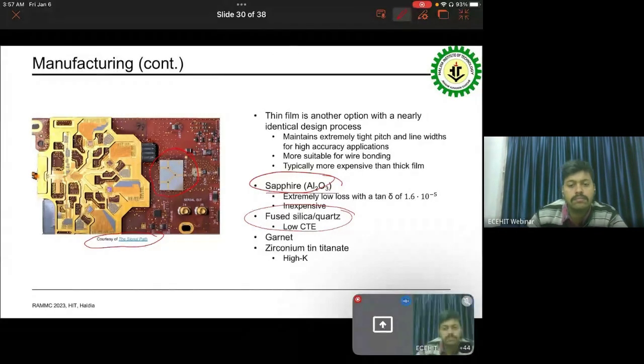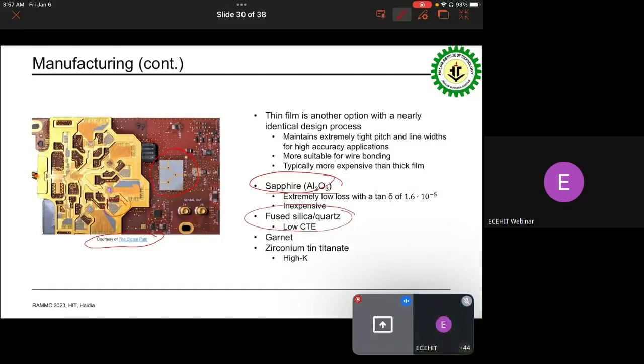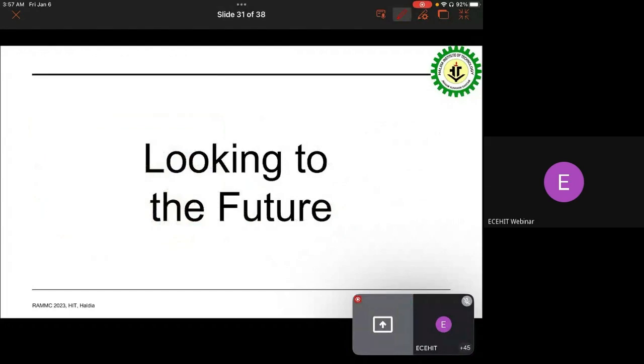So integration of thick film, and then down in here you have thin film components. This one you can see is surface mounted to the PCB in 5 different locations. This is a modified Wilkinson splitter. And then down here you have your thin film component. This is going to be wire bonded out to the traces as needed. So there is some hybrid mechanisms involved that we very often use.